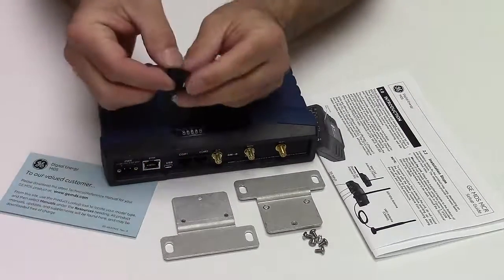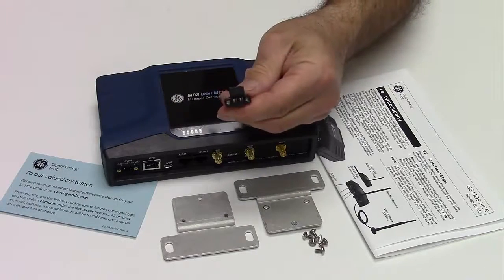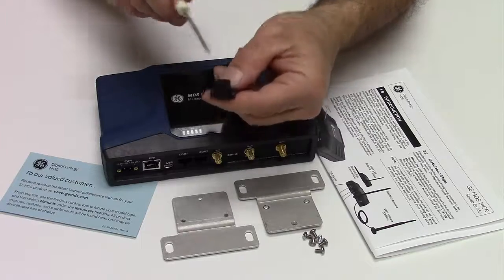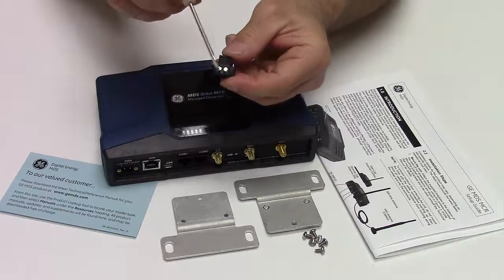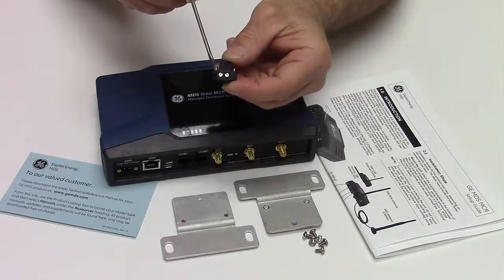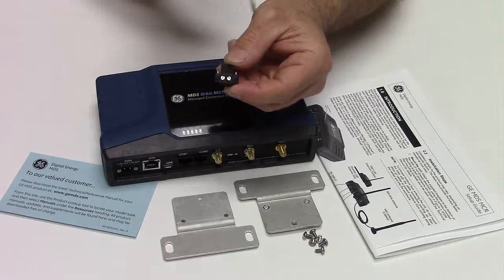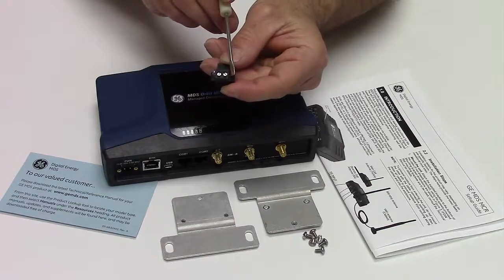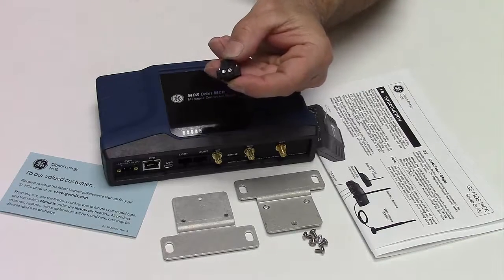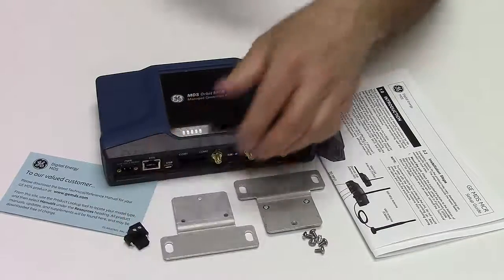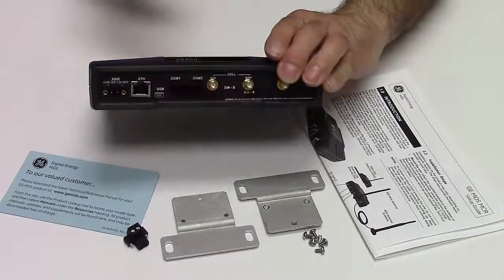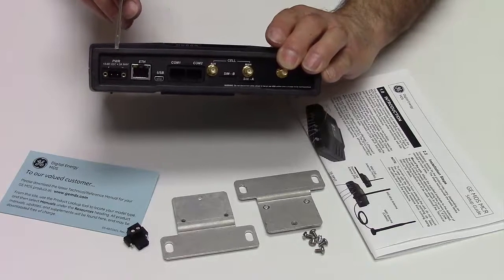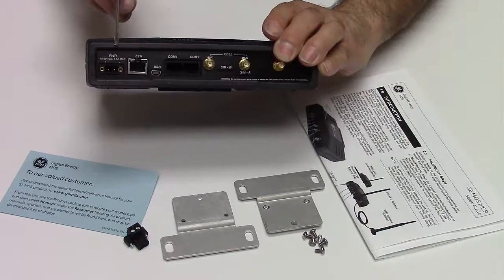The DC power connector is a 2-pin locking type with 2 screws for securing it to the chassis. There are also 2 binding screws at the top of the connector for securing the wires from the power source. The left side is positive and the right side negative. This is fully covered in the Quick Start Guide. As indicated on the front of the chassis, power input voltage is from 10 to 60 volts DC at a maximum draw of 4.5 amperes.